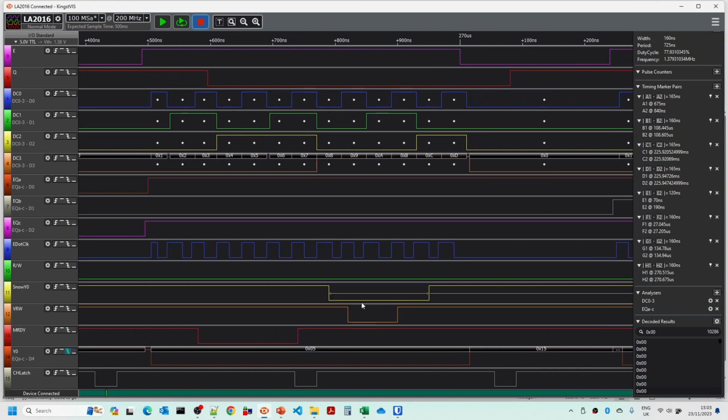So what we should be able to do is to replace the current feeds of the Y0 signal and the video read-write signal from the current address decoder with these signals generated by this circuit, and it should just allow the updates to the video RAM not to generate the snow that we've been seeing previously.